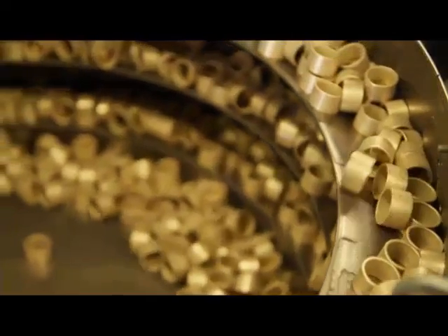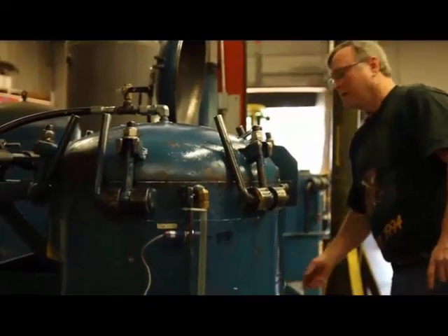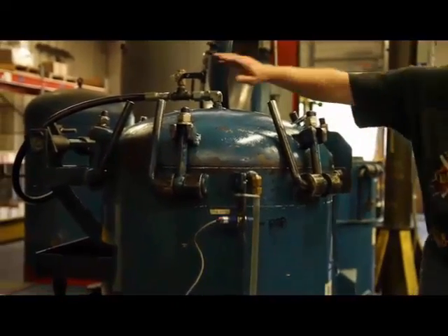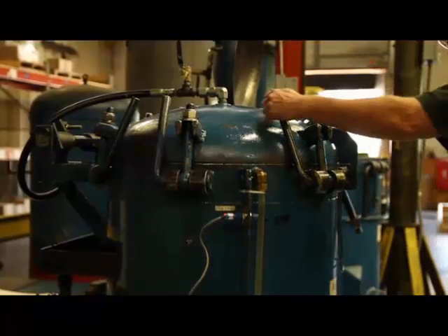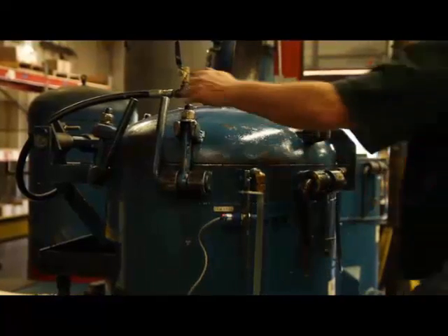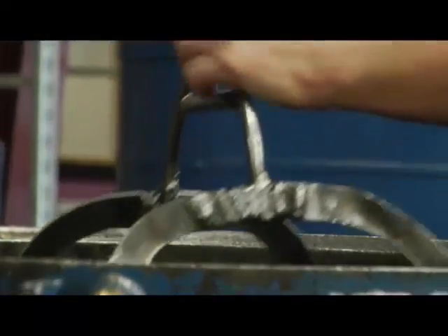Under vacuum, the air is drawn out of the interconnecting pores in the part and is replaced by the customer-specific oil. The oil is retained in the bearing's sponge-like inner structure. This process not only prohibits rust, but provides adequate lubrication as the bearing is in use, preventing wear and in many cases eliminating the expense of other lubricating aids.